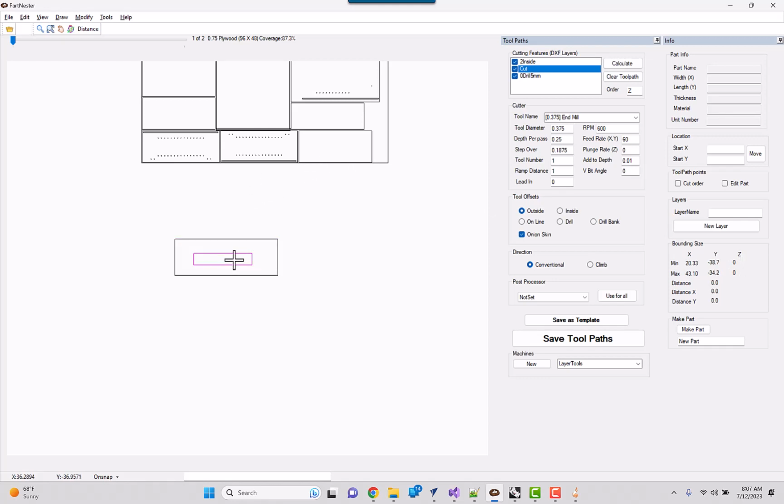We could do the same thing for the interior component. So going to modify, move, selecting the base point of 0, 0, 0, and I want to move that down to 0, 0, if I only wanted to go 3/8 of an inch deep, specifying -0.375, then enter.